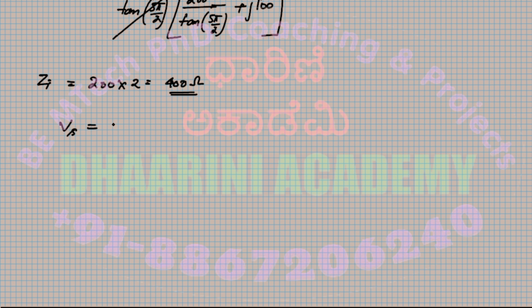It says voltage across any resistor is equal to the main voltage, which is the supply voltage, correct? That's equal to 200 into the resistance across which you are trying to measure the voltage, that is 400, whole divided by the sum of every resistance that is present. So there is a 200 ohm resistor, internal resistance, plus this one which is 400. So that will be the value of Vs. Yeah, please calculate.